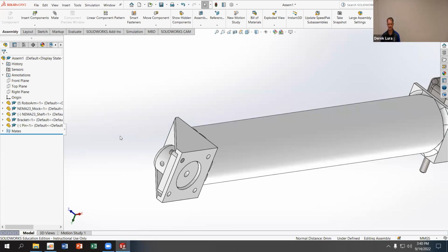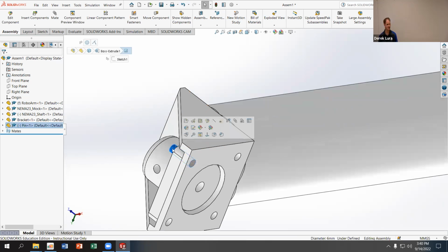And that pin is going to be underdefined, but it's just going to be able to rotate in position, so I don't really care. You could fix that by adding an additional mate, but since it's not going to change my simulation, I'm not going to bother with it. Being able to rotate is not going to change the performance of the assembly in any way. So generally, if the rotation doesn't change the geometry, it's not worth adding the additional constraint.